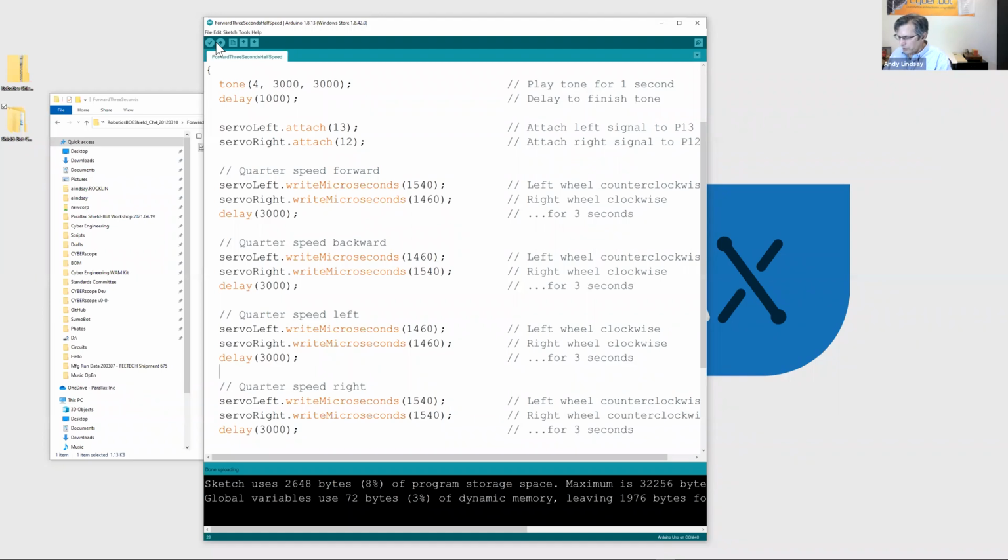And then another interesting maneuver is the curve. All you really need for that is one wheel speed to be somewhat less than the other. The smaller a fraction the left wheel speed is of the right wheel speed, the tighter the curve. You can use that to go in circles and other fun things.